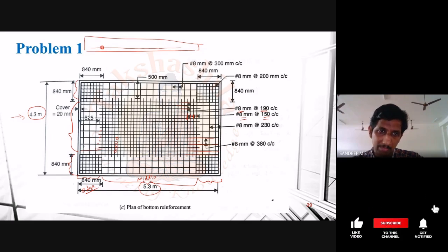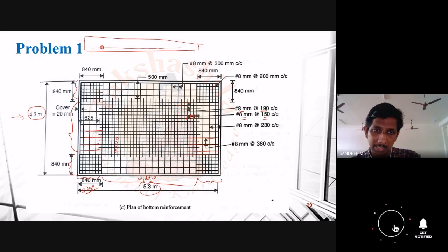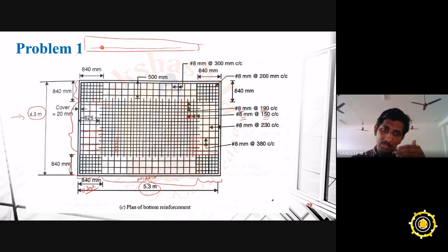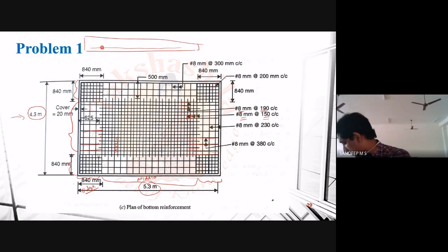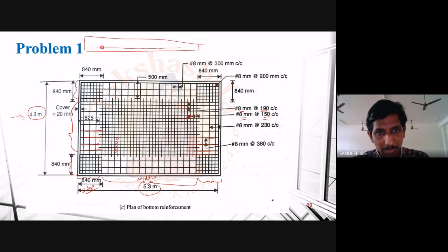If you see that we have reinforcement provided like this way also in the edge strips. Okay. So that reinforcement also should be provided in this, along with the reinforcement that you have provided in the middle strip. Okay, in a similar fashion, we will be having edge strips in the other direction also. So the reinforcement which we had designed should be provided there also.